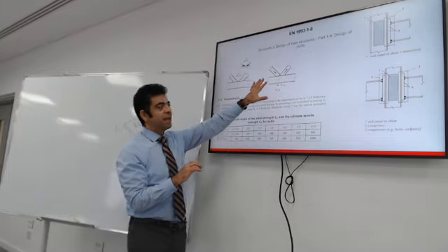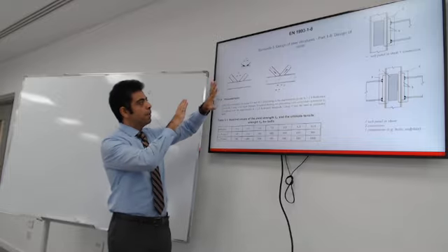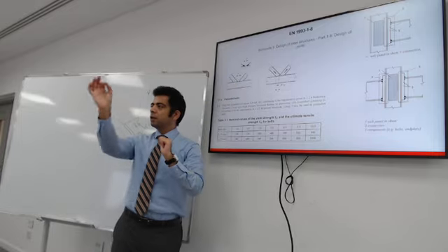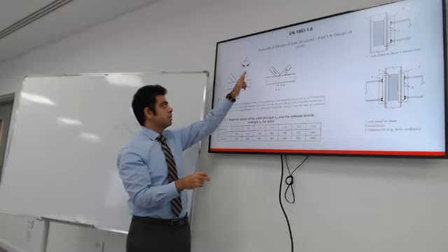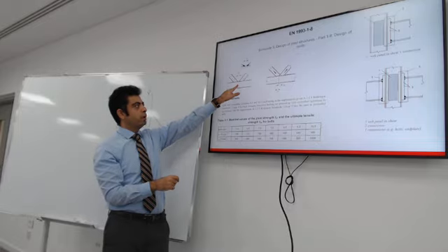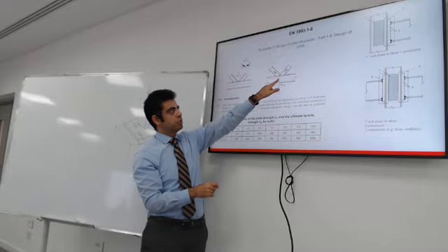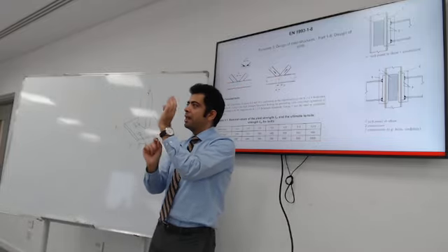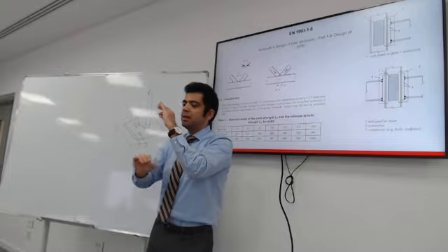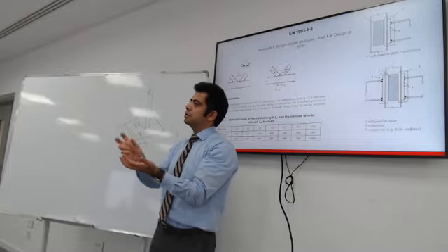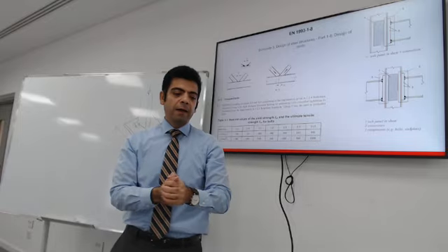But when you're detailing it, you need to pay attention. Do the center lines of the members all meet at one point, or is there an actual eccentricity? The diagonals meet at a point that has a different location than the center line of the chord. This will introduce some eccentricity that you need to take into account.